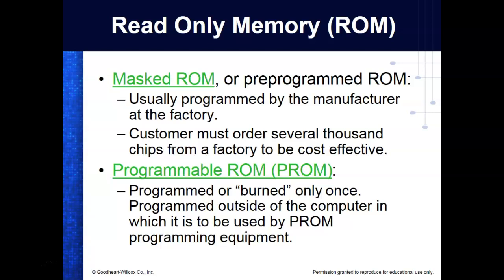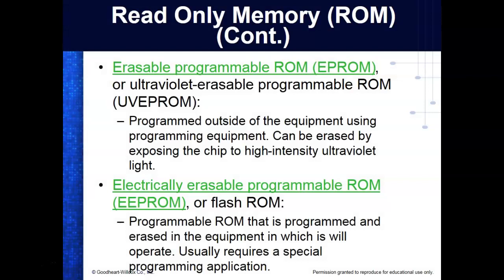So once you've blown a fuse, it's what? It's blown, right? You understand that? So those guys were one-shot deals, which means you programmed them, and if you wanted to reprogram, you'd take that out and throw it away, and put another one in there. So that's why we hook a computer up to it, so we could save the programs in there. Then we went to erasable programmable read-only memory. These guys right here.